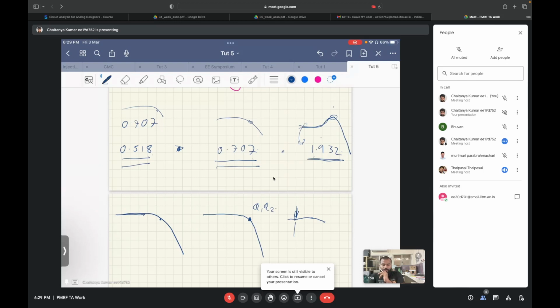Yes, sir. In the biquad 3, that resistance value will get decreased, the capacitance will increase. So that 518 ohms... sorry, 5.18 kilo ohms it will be, right? Yes, sir. It will decrease, sir. Yeah, so that's what I am saying.